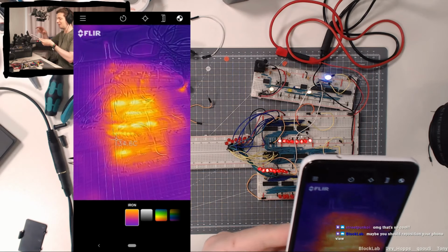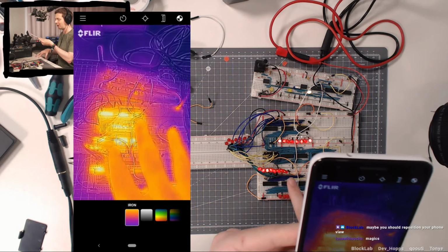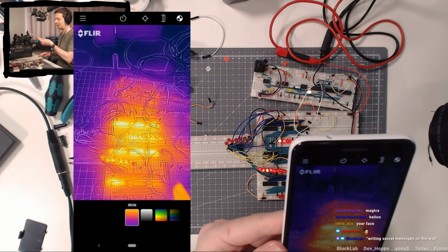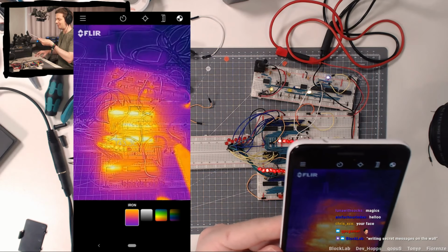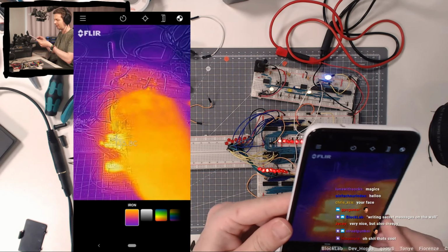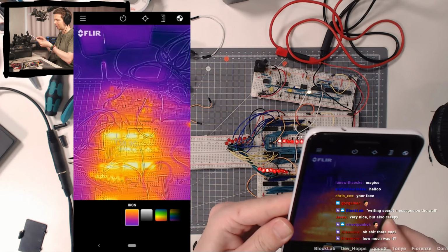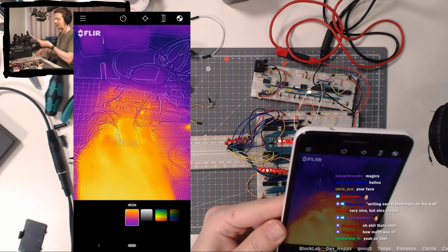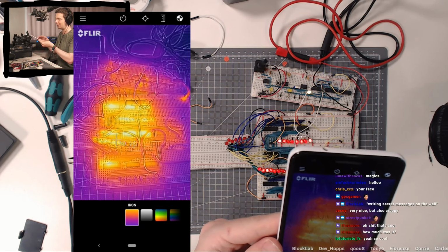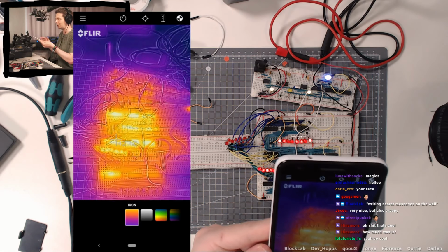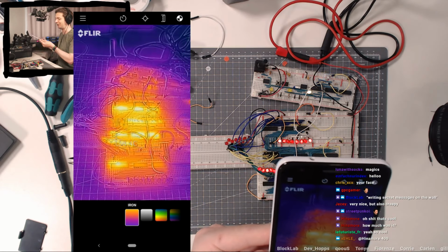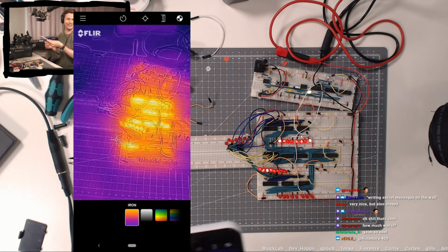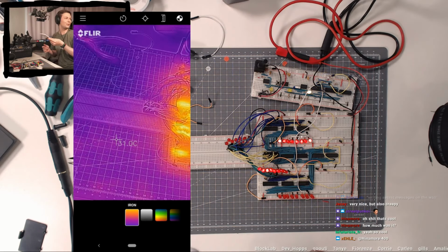What a toy. Well, the hope is that if we have overheating components because we connected them wrong, we would be able to see that and see them spiking up extremely. Right now these chips are just like 44 degrees, and this room is already pretty warm, so that's perfectly fine. But if it would get up to 50, 60 or 70 degrees, we would know, oh crap, this chip has a problem. And so we can use that for debugging. At least that's what I tell myself and how I justify the cost. It's like 380 euros or so.